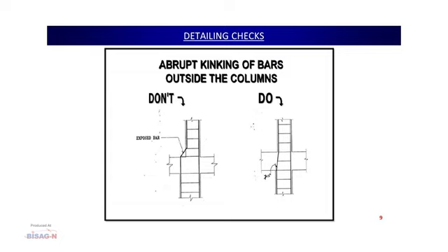In this case, what the bar binder intends to do is continue the column bar to the top, and from the outside itself, not even inside, they bend the bar and continue inside the top story column. That exposed portion later on they cover with some kind of concreting, like a haunch portion on the outside, which has no structural meaning at all.